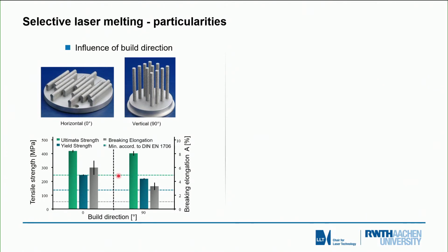So that can be even increased. We can even get higher values by corresponding resolidification tailoring. So if we adjust the solidification by the knowledge of the metallurgy, we can tailor the properties in terms of these mechanical behaviors and characteristics, also locally to the individual part. That's really unique, and you won't find that with any other production method.